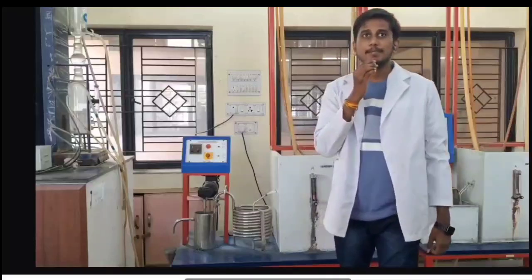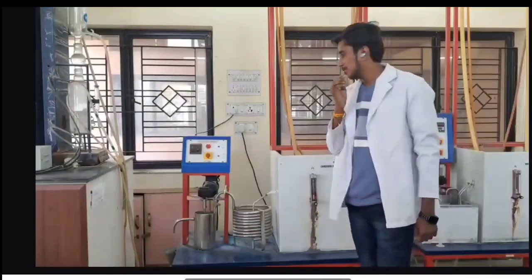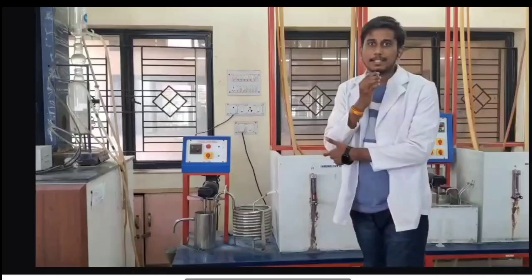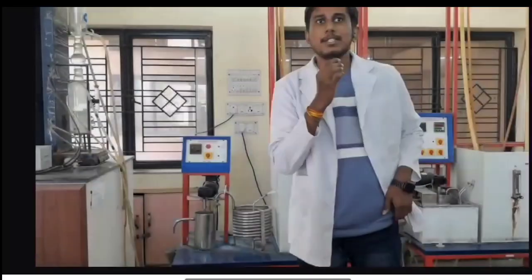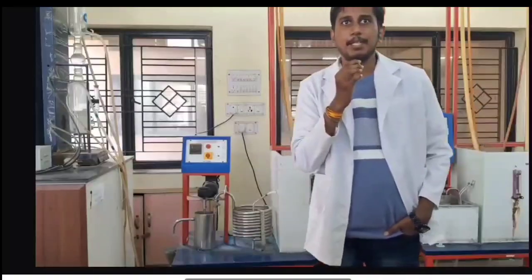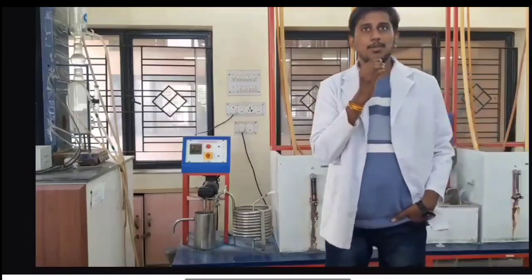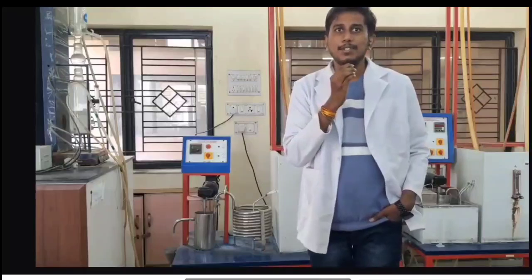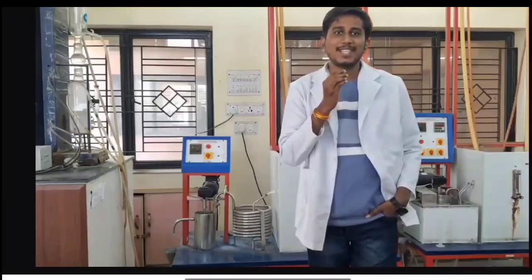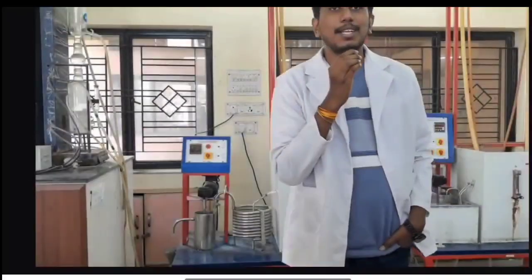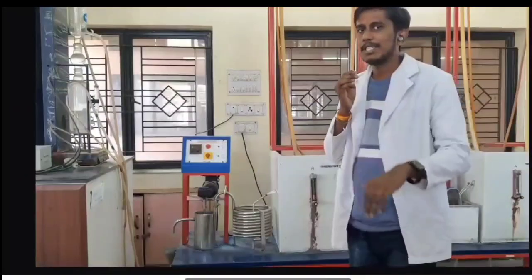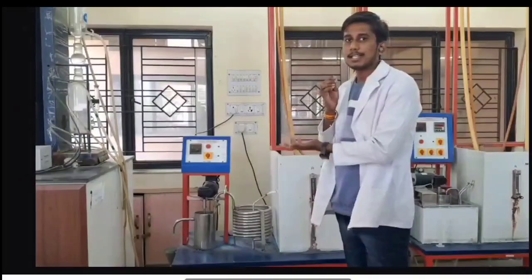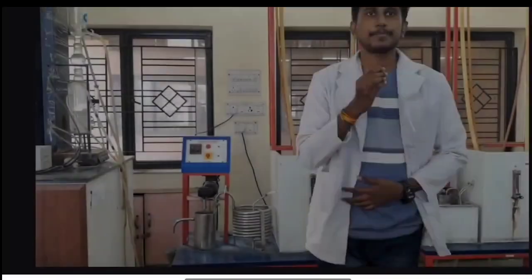Our first step is preparing 20 liters each of NaOH solution and ethyl acetate solution in the tanks, which feed the two reactors for our experiment. The exact concentration of each solution is crucial because the reaction rate and the conversion calculations depend on the initial conditions. So let us discuss in more detail the reactors we are using in this experiment.